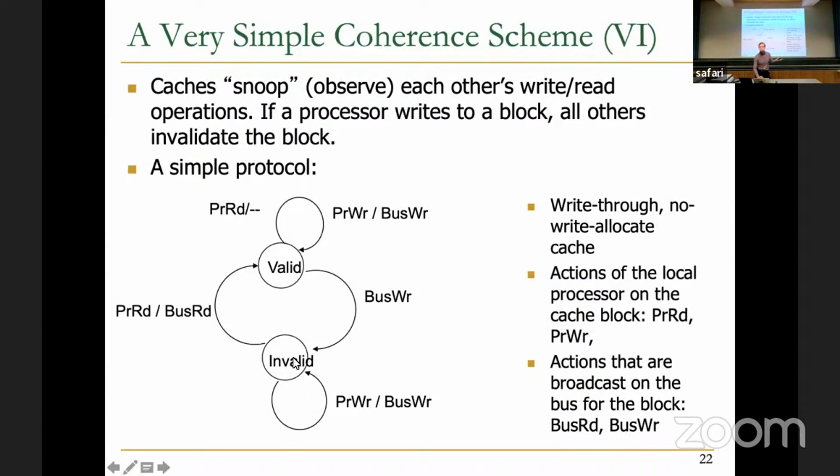Hopefully that makes sense, right? And the key here is the memory is already updated. Whenever you write to a block, memory is also updated. So there's no, let's say, dirty or modified state in this particular protocol because we assumed write-through caches. Right? We're going to relax that assumption later on.